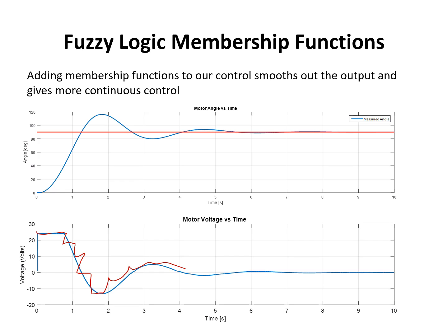Tuning this is now slightly different. You can't typically use analytical equations to tune it. You have to change your membership levels. So instead of saying 10 and 20 degrees, in this case for the absolute error terms, instead of saying the error above 5 or 10 degrees, we can make the error smaller, or make the voltage levels output from the different functions a little bit higher or lower to get a lower overshoot or faster response time in essence. So it's perhaps slightly more difficult to tune, but it's very easy to implement in essence.